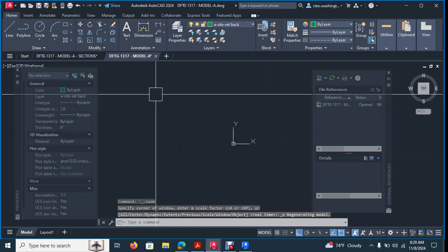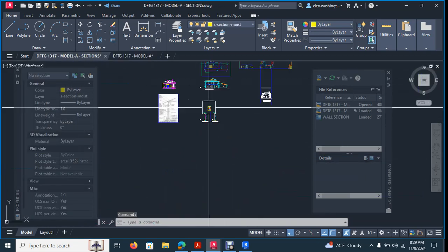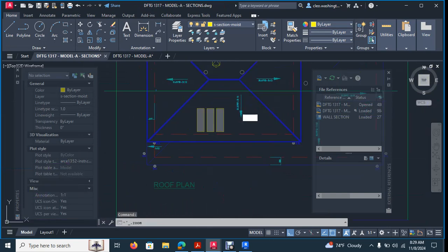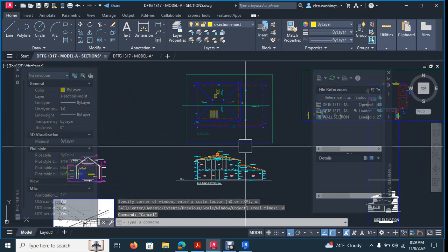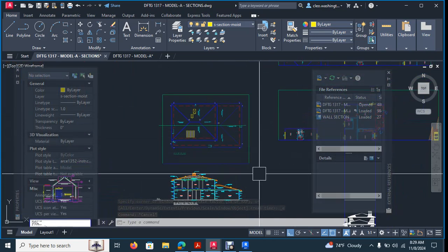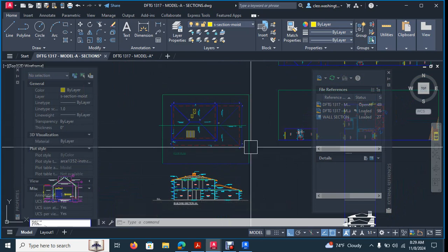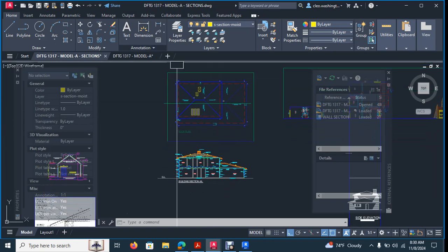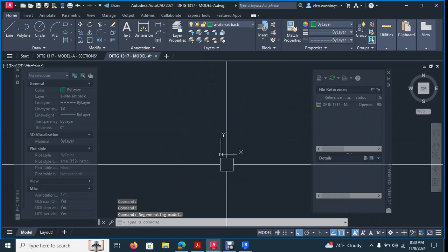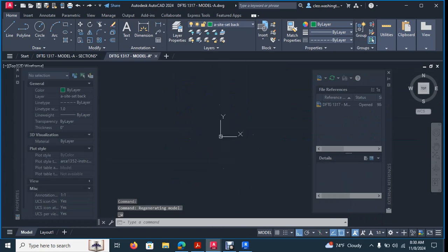Okay, so typically when we drew the sections, we X-reference these drawings in. For this one, because we're doing interior elevations, we don't have to X-reference them in, but I will do that for sections because we need to make sure that things are not moving. In most cases, if something does change on the interior elevation, the time that it requires to make an interior change is so minimal that it's not really pertinent. You know what I'm saying? You can make these updates in 5 minutes, right? So for this one, we're just going to utilize the drawings that are already in the drawing file, okay?